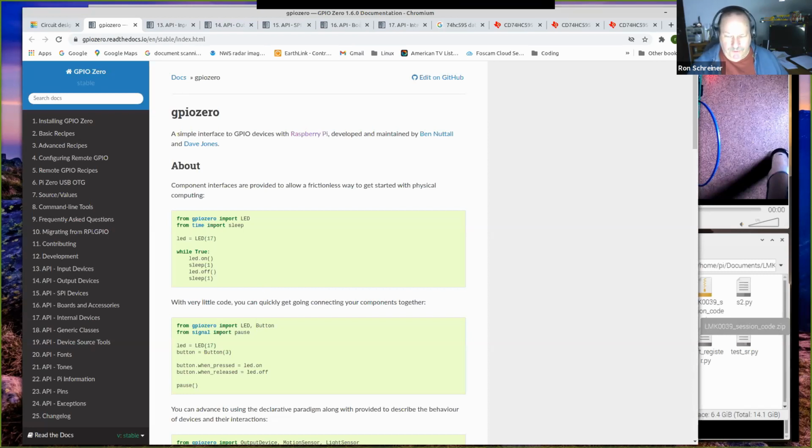There's also the other thing that you find out in GPIO land, which is there are at least 3 different naming conventions for the pins. It has some way of realizing that if you put a number in there like that, it knows you're using a particular naming pattern. Again, I don't have to specifically tell the module which one of those to use. It figures it out. The only downside to gpiozero is that, because there's a whole bunch going on underneath the hood, it may not be the highest performance module. So if you have a performance issue, you might need to look at one of the other libraries that's closer to the hardware.